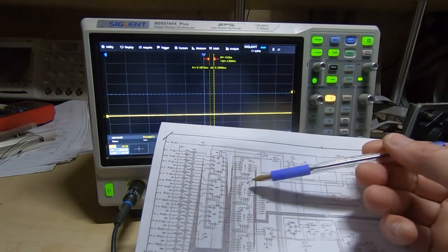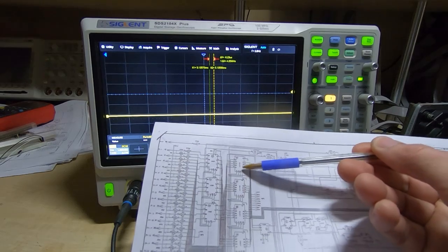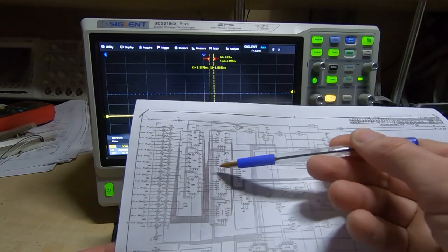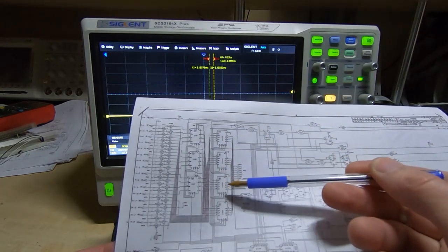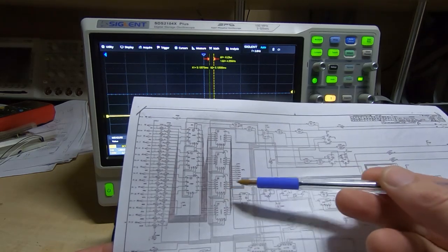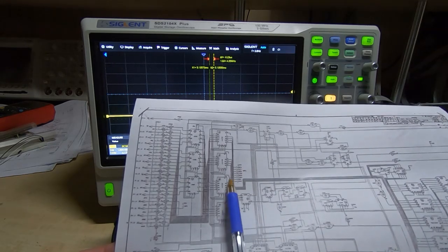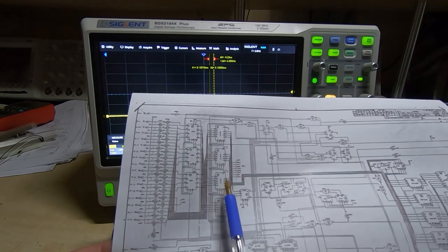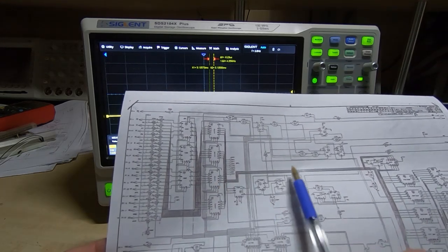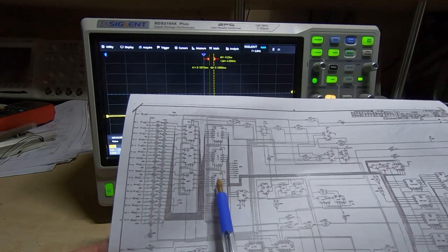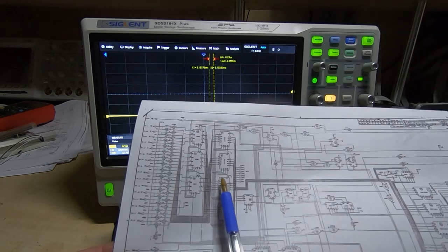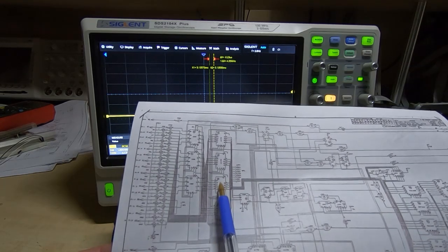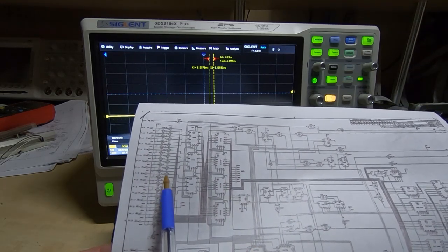And just to clarify that, we get 2 bytes in effect of data for the characters, but only one of these pairs is responsible for passing control characters, and I think it's a control character that we are looking for here, and that goes through these 2 devices. And because of the particular control character that is causing it to do what I think it's doing, that has to come through this device, and this is U38, so I'm pretty sure it's either this or we've got some strange issue with the buffer.